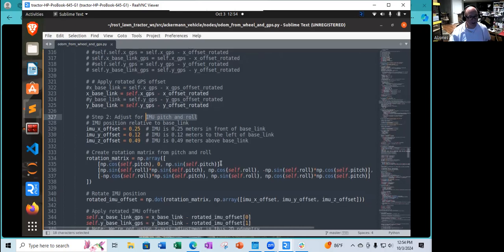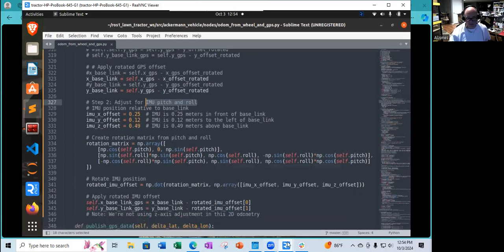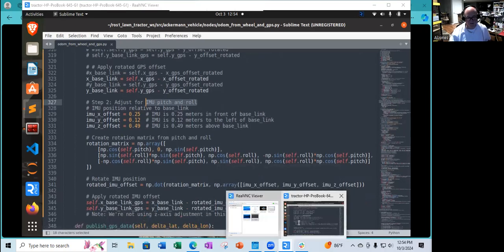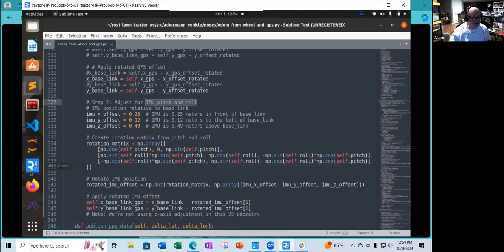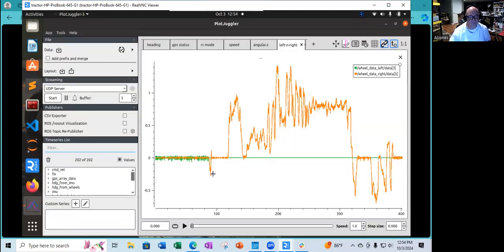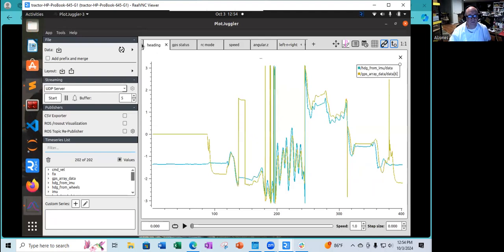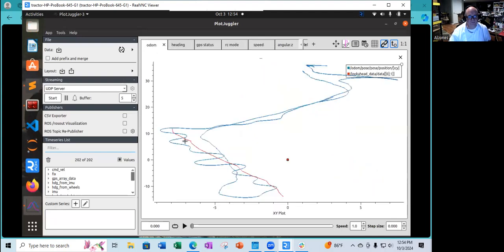So I put the code in there and went out and ran a test, and I know it will shock you that the test didn't go the way that I wanted, and basically I'm getting this weaving. The blue pattern is actual, the red pattern is in this particular case look ahead data, which effectively is the track it's supposed to be following.